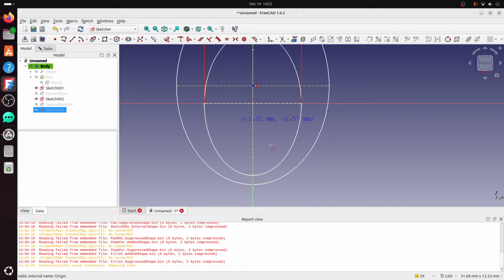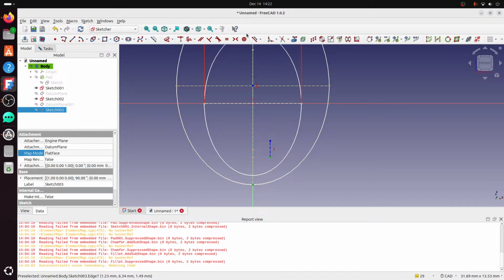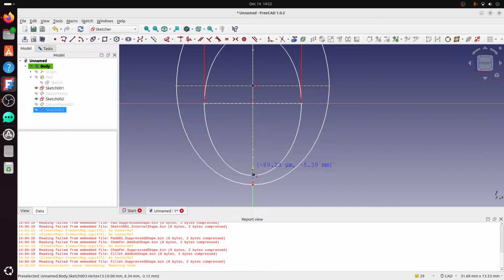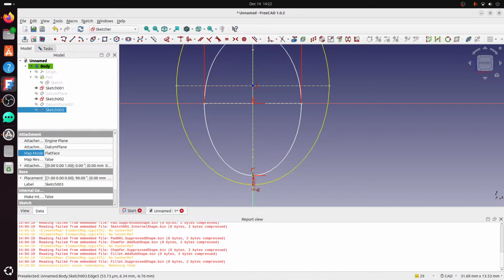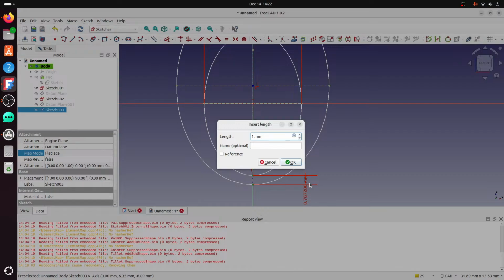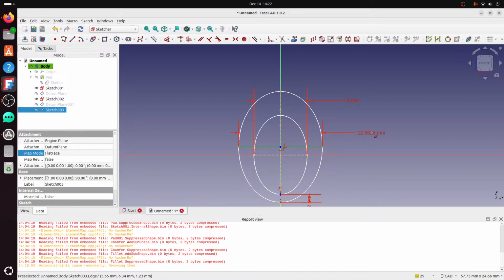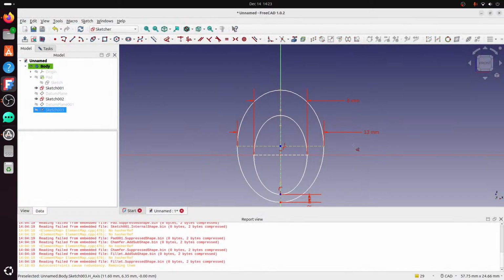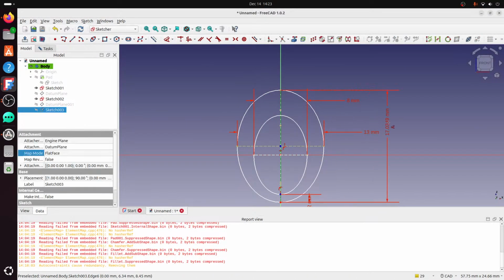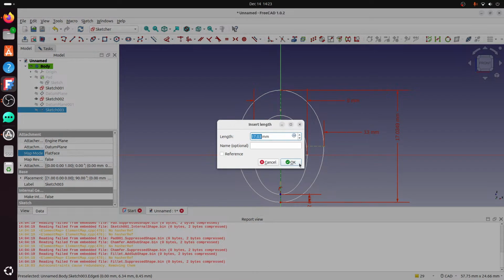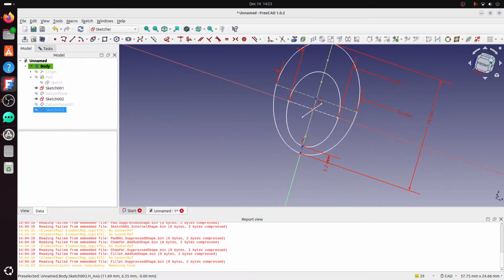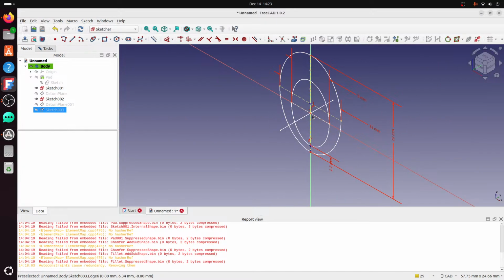But what I want to do is I want to make that wall like 3 walls thick when I print it, and I know I got a 0.4 nozzle. So I'm going to make this distance 1.2 millimeters. And then I can come back here, do this. Let's make that 13. Make it about a 1/2 inch wide. And then 18 is probably a good number for that. And now when I pad that, it's gonna have this hollow cavity in there.